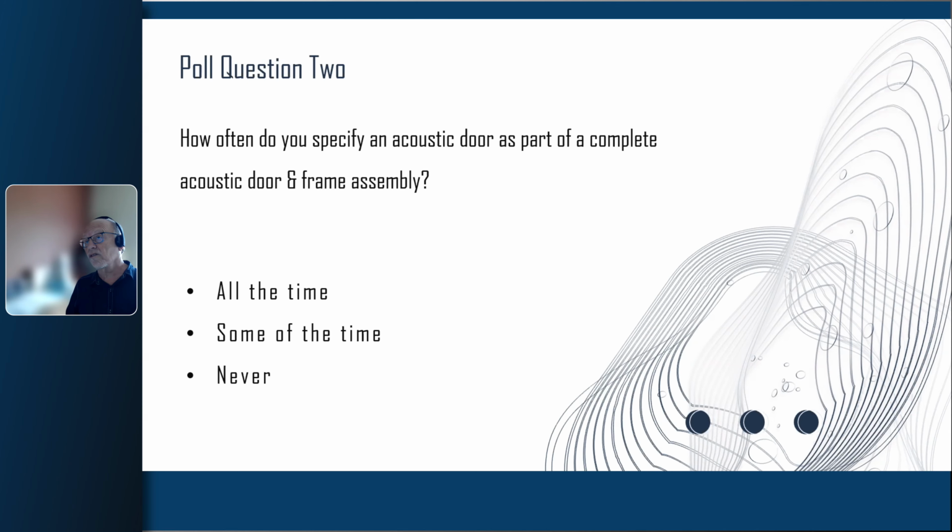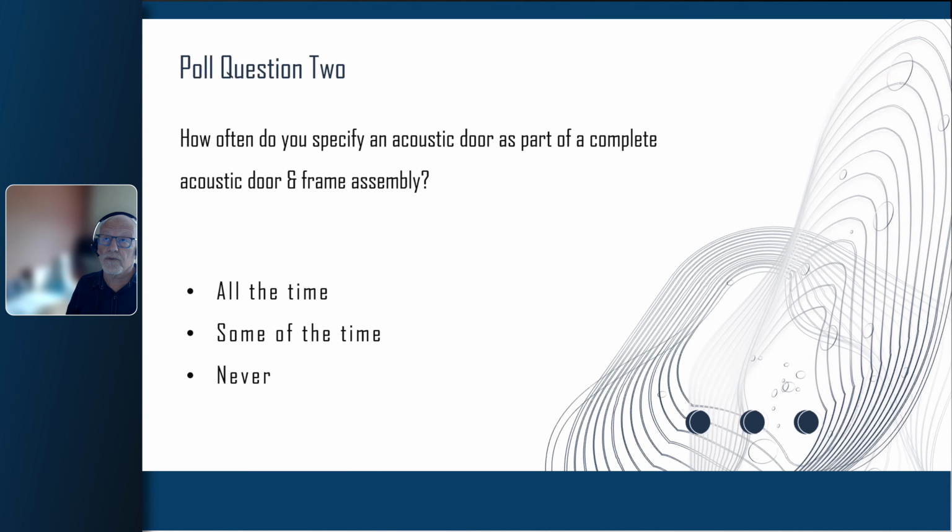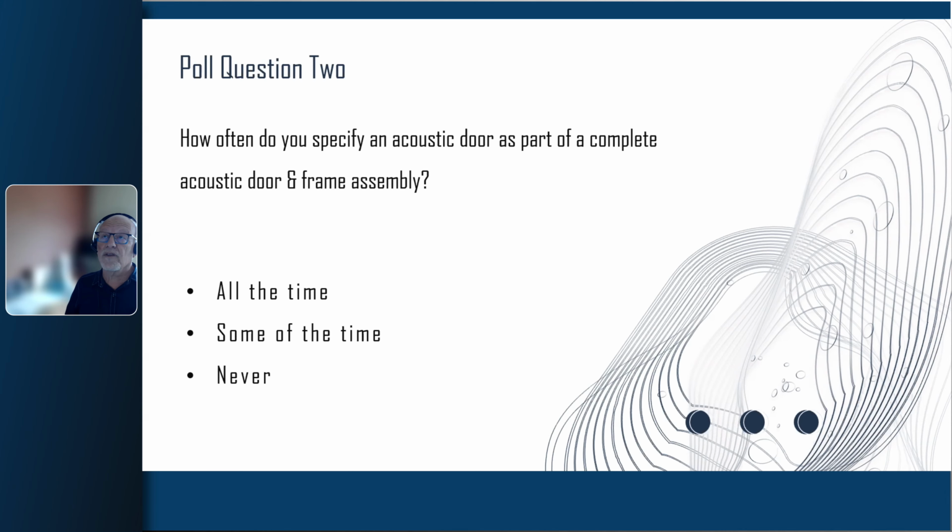If you go down to an STC 40, the difference that's allowable is only 3 decibels. So as you get lower and lower, the field performance criteria are less severe. As you go higher, obviously the reverse is true. They point to different things.